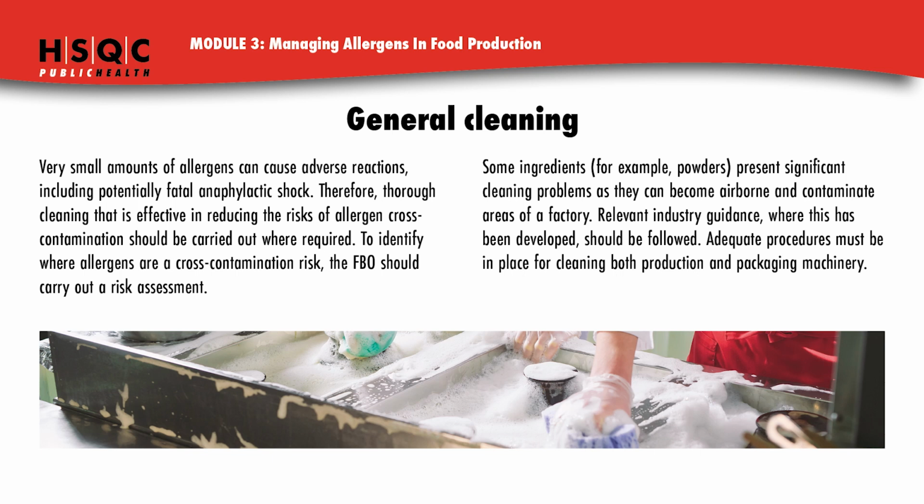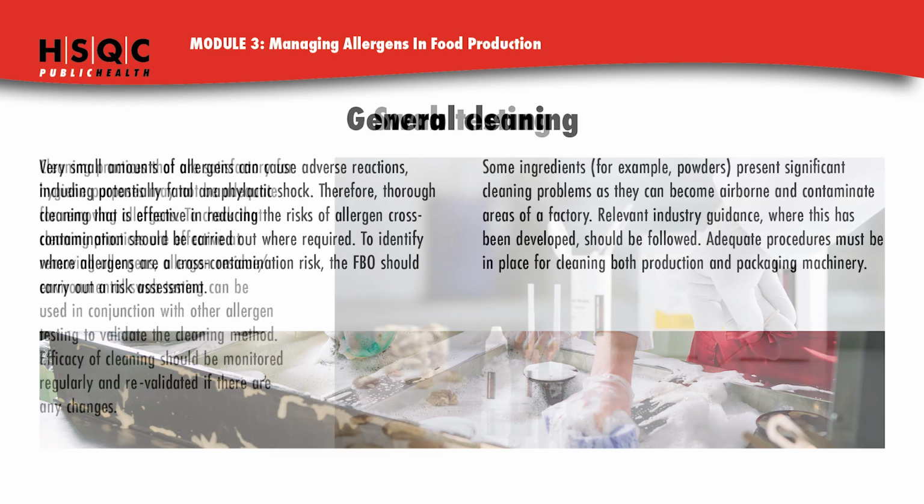Some ingredients, for example powders, present significant cleaning problems as they can become airborne and contaminate areas of a factory. Relevant industry guidance, where this has been developed, should be followed. Adequate procedures must be in place for cleaning both production and packaging machinery.